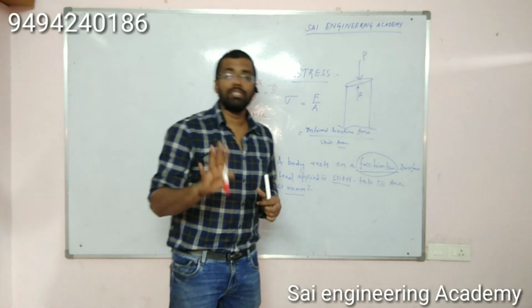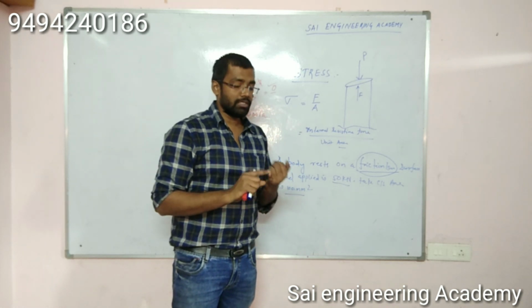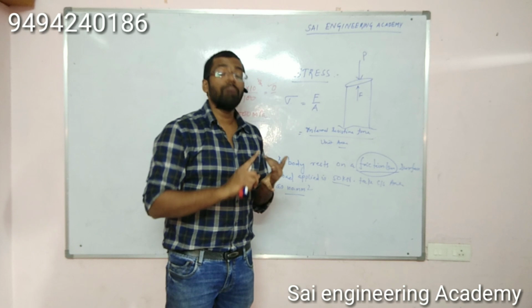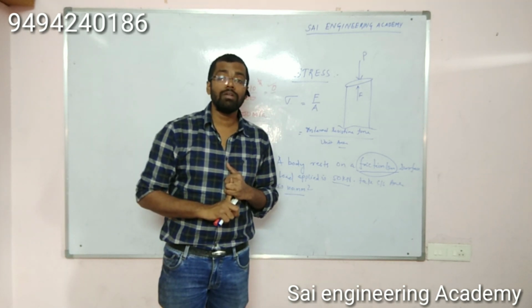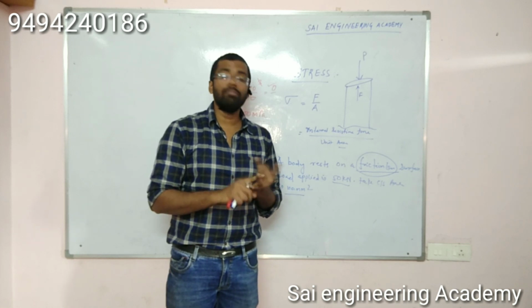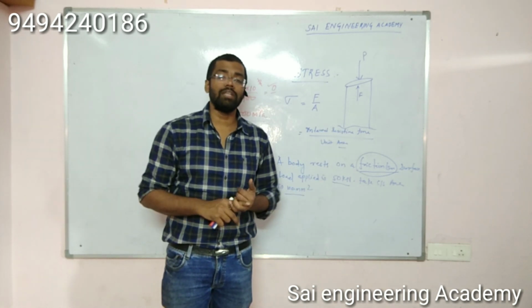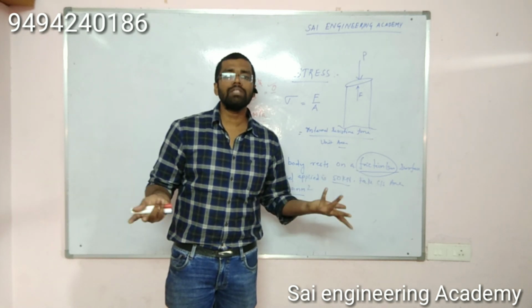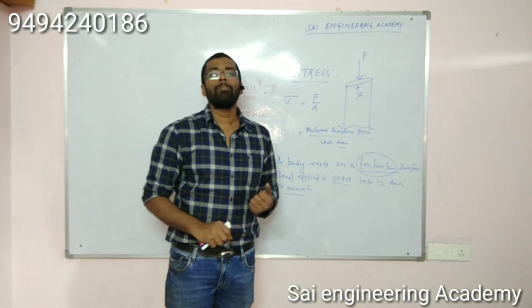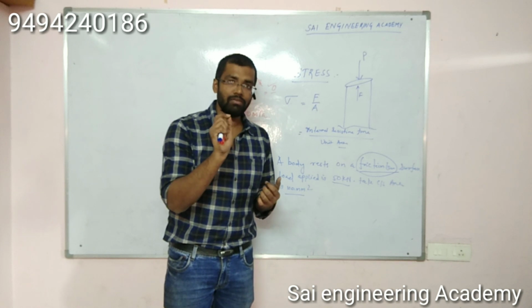These are some of the things you should remember. A body resting on a frictionless surface, or a body free to expand. Suppose you are applying a temperature load, thermal stresses, and the body is not constrained. It is free to move, free to expand in both directions. What is the stress developed? Zero. So read the question very carefully.